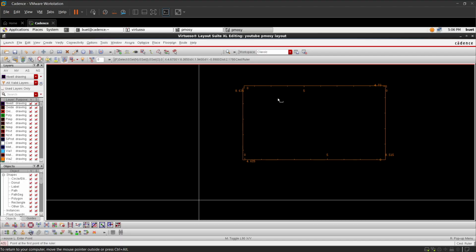Oxide layer will help you isolate this part from the substrate you have been using. By default, we have been using a P substrate at the background. Whatever the black screen you have been seeing is a P substrate. In that, we are supposed to do our layout. So this will go OD. Next, there will be gate formation, and this has to be done by using etching.